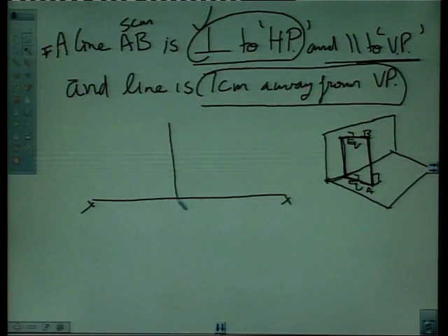Say this is point A, this is point B, this is line AB in elevation, and as its length is 5, you should dimension it here like this. You should write like this, 5 centimeter. Again, dark 5 mm thick text.